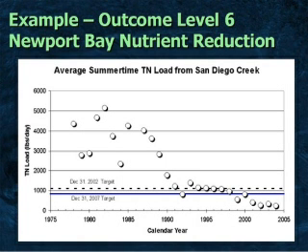In the 90s, in the early to mid portion, a major regional BMP was put in place, called the San Joaquin Marsh System. Essentially, it takes a very large portion of the creek water, runs it through the marsh, which removes a large portion of the nutrient load, and then puts it back into San Diego Creek. So you have a major regulatory action and a very large BMP. Also in the 90s, in 91 in particular, you receive your first stormwater permits. So you're starting to see some additional work in the stormwater area, looking at urban discharges.